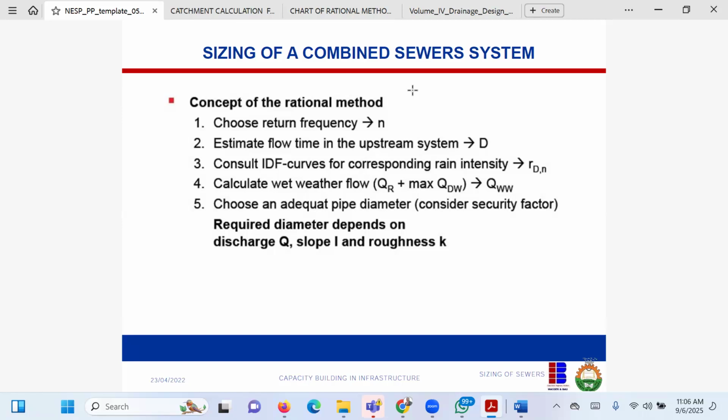If you start going to 5 years, 10 years, you start going 100, 120. Most states in the north don't even exceed 120. That's why the only place you hear about flooding in the north are those communities that are within the catchment of the River Niger, and it has to do with overflow of the banks. For me, that is what causes flooding: overflow, or dam break, or dam overflow.